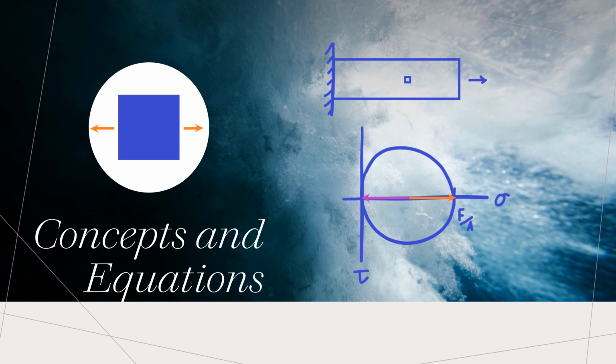And in order for my components to reflect that on my Mohr circle, I had to rotate it an entire 180 degrees for my y to reach that location again. Meanwhile, I only had to rotate it 90 degrees for the actual element itself.